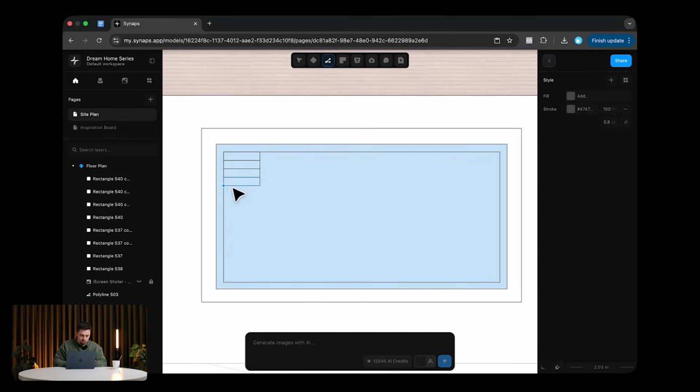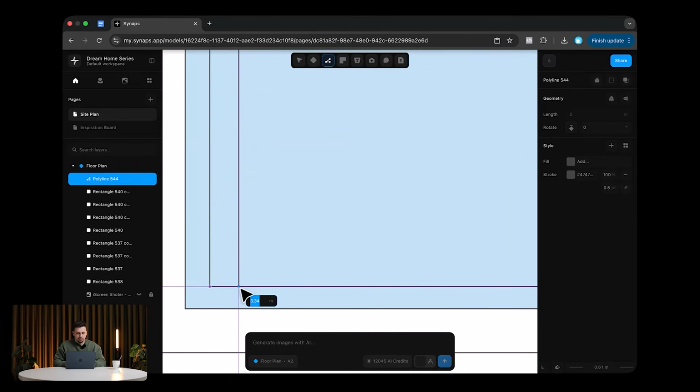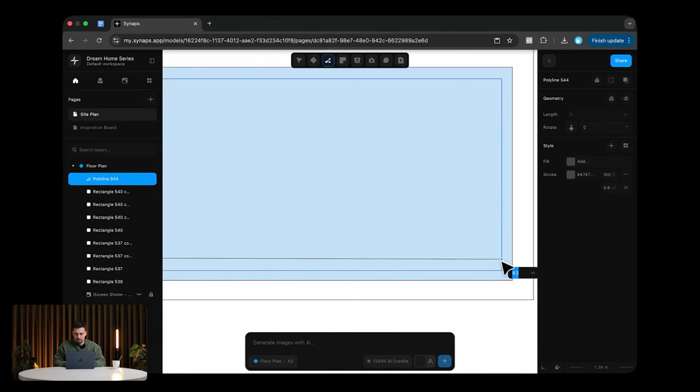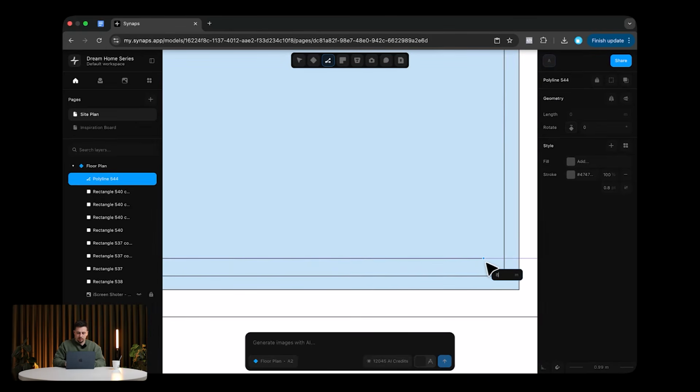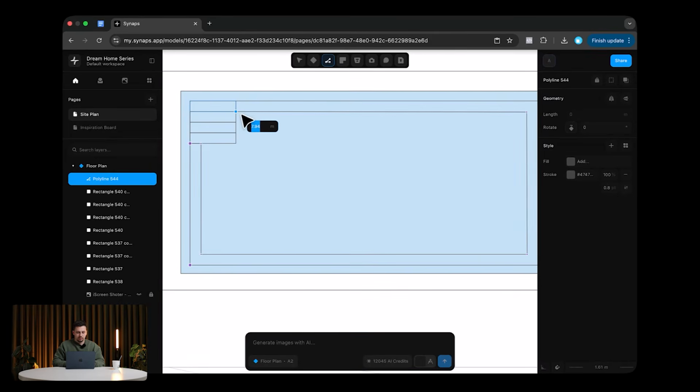And then we can do something like a step throughout the whole pool, which would be 30 centimeters. So if up to here it's 3.34, then we need 3.04. And if it's 9.2 here, we need 8.9. And then if it is 4.2 here, we need 3.9. And then we can close this off.